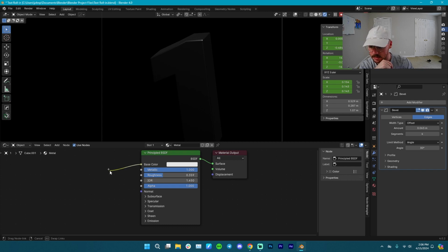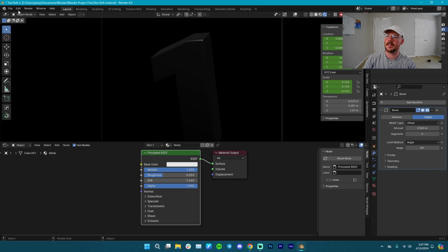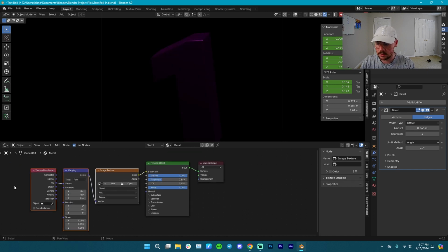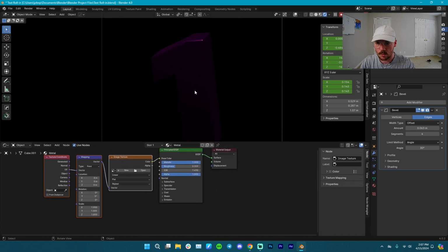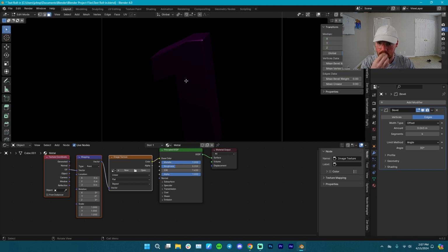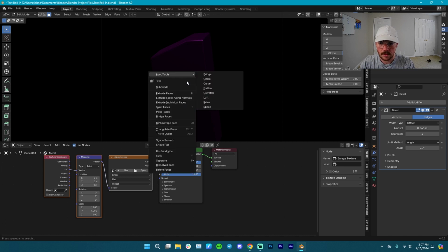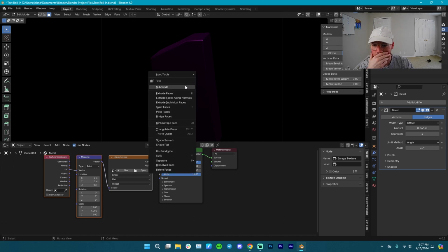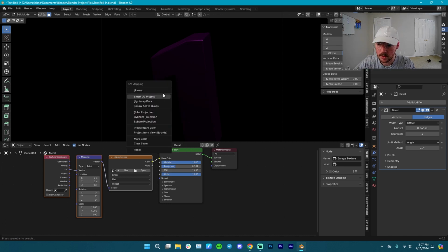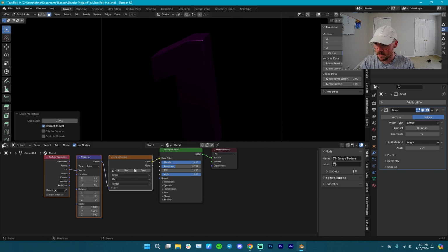Now you can either drag out from base image and select image texture, or if you have in settings the Node Wrangler add-on, you can just hit Control T and it should add an image and a mapping texture. Then clicking on R1, hitting tab, right clicking, and hitting U, and then just cube projection should be fine.